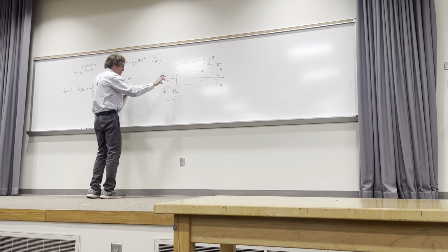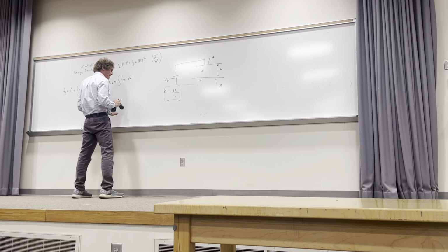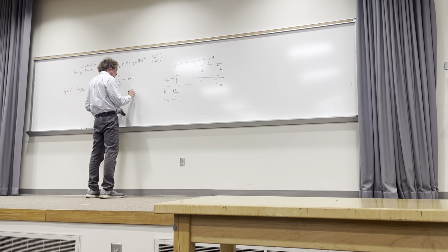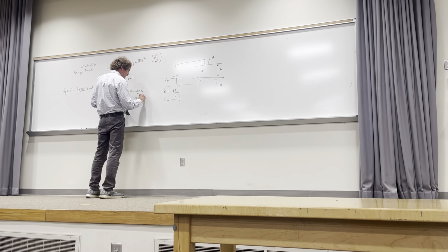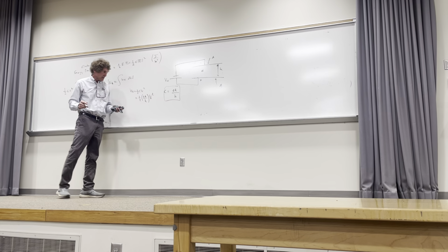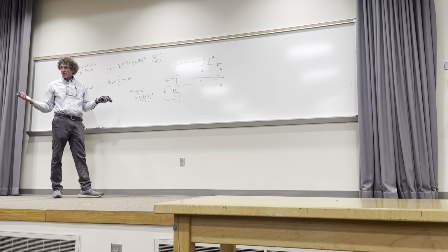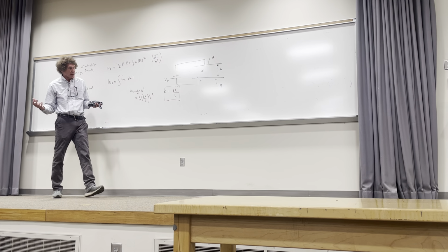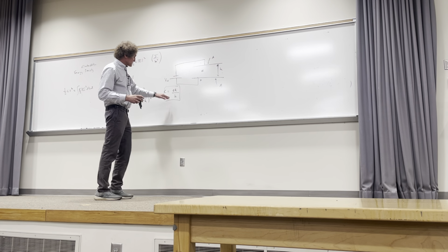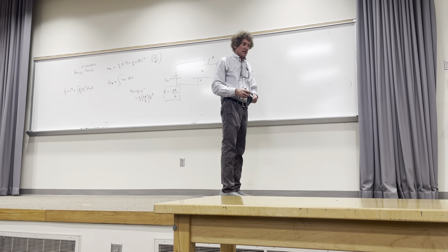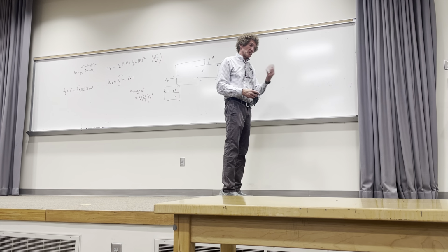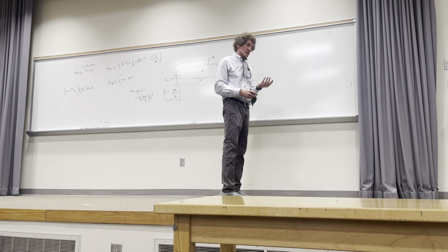So the energy, just from this form of the energy calculation, the energy in that capacitor would be equal to 1/2 CV squared, or 1/2 epsilon A over H times V squared. Y'all with me? I'm just putting down what it's equated to. Whatever V is, that should be the energy. Now, we got the capacitance before by assuming the voltage, then getting the E field, then getting D, finally rho S, then the charge, and saying capacitance was Q over V.